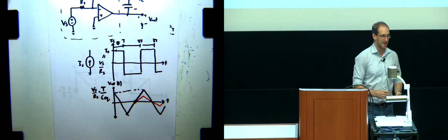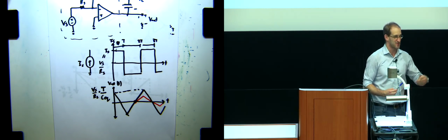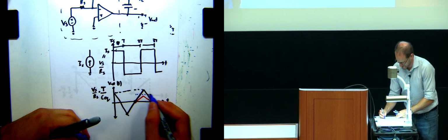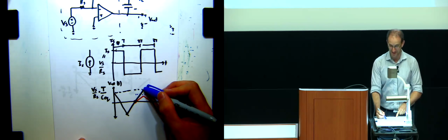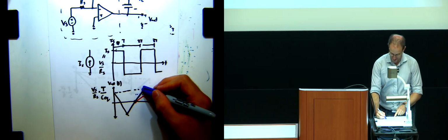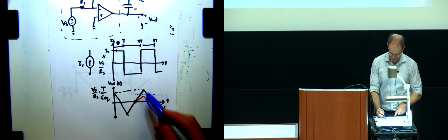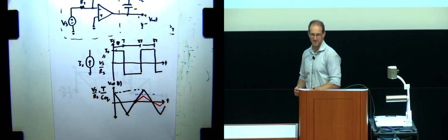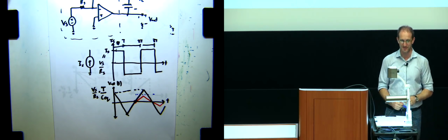And if this is really what happens, then life is pretty straightforward. It basically works very much like we described before with the switches and everything, right? We would put some Vref as an example over here. And if you see that this waveform crosses the Vref, if we look at the output after the comparator, you would see a blip high here, or blip low, in fact, in that case. And when it's below, then you're fine. Meaning you detect the touch based on whether or not you actually cross this reference level. All right?